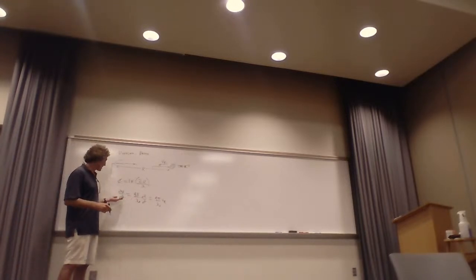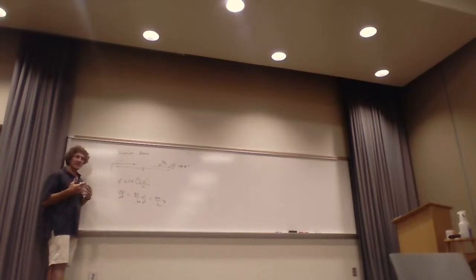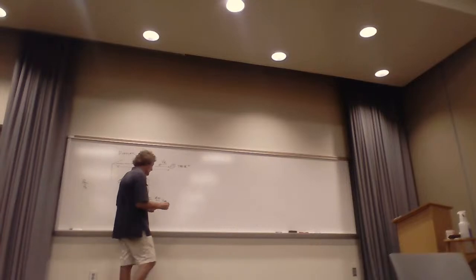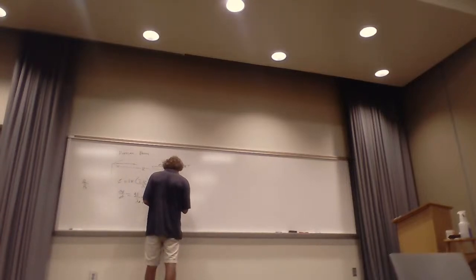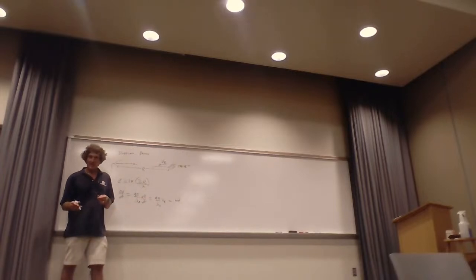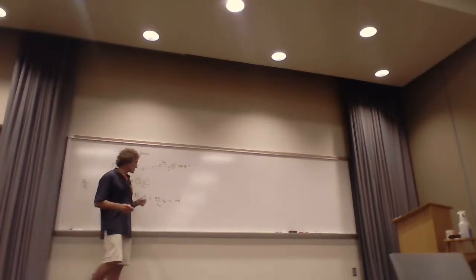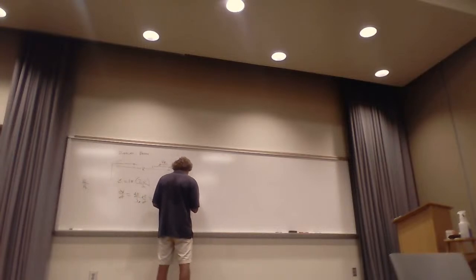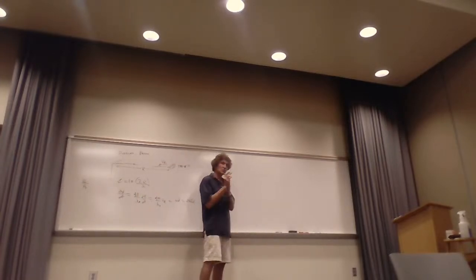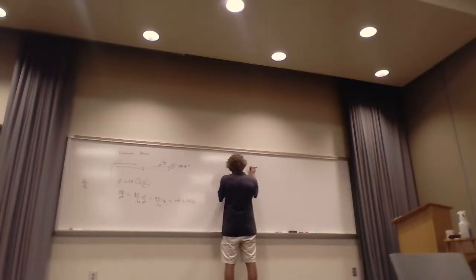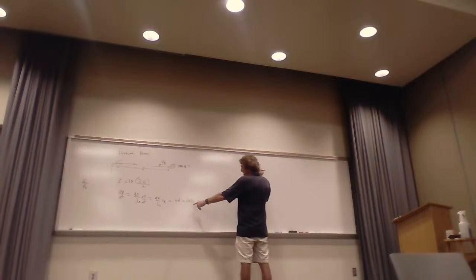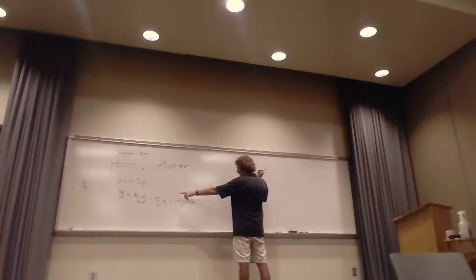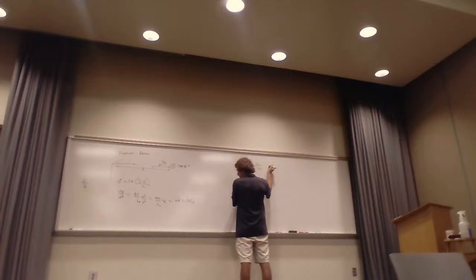Well, just think about this. The time rate of change of the angle phi with respect to t would be a small omega Doppler, in radians per second. And that's equal to 2 pi f Doppler, or the actual shift in the Doppler frequency. So the Doppler frequency is equal to, if you look at this, I can divide 2 pi into the 4 pi, and I get 2. It's 2 over lambda naught, and I like to do it this way, times Vr.